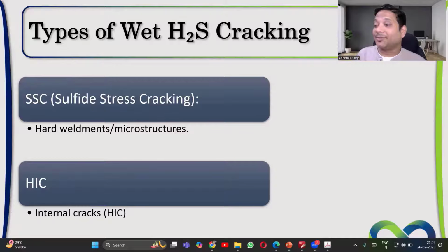Yes, Vimal is saying during shutdown there won't be any stress present. Right, because there is no pressure. So that time HIC will be more prevalent. If it is cracking, it will crack because of HIC. Or when you are coming down, at 60 degrees Celsius and still there is pressure, we have not relieved the pressure, only the temperature has gone down, that time it may happen. SSC will happen when both of them are present. HIC will happen when only one of them is there: only hydrogen, not stresses.